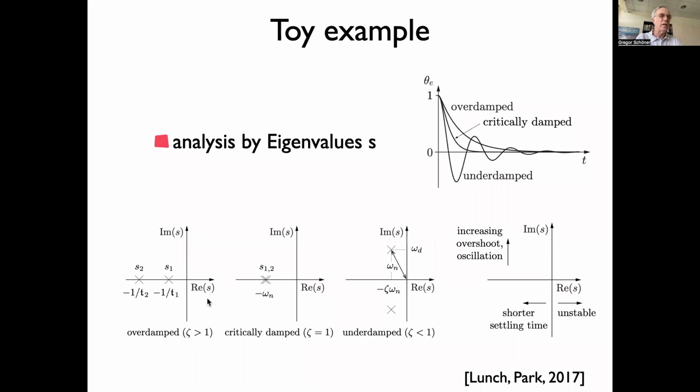The design of these kinds of control laws is based on essentially linear system thinking. You approximate the whole system, the control loop and the plant, linearly around the desired state. So you linearize the whole equation, and then it would have solutions like a harmonic oscillator. A harmonic oscillator is really second order, a second order differential equation, which is the physical form of the equation of motion, as I showed you. And a linear second order equation is generally a forced damped